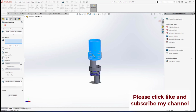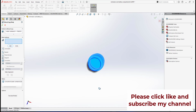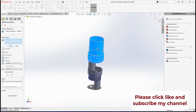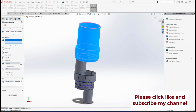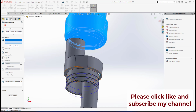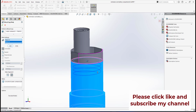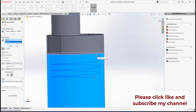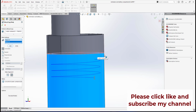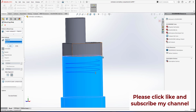Alright, my next setting is that the water container and the mist making unit are now in line in terms of concentric. Now I need to move it. I select the second mate setting. I will select the face of this water container, and it goes in that direction. But remember in my previous video, I need a gap here, because the gap is for the rubber sealant or silicone sealant, about 1 millimeter.